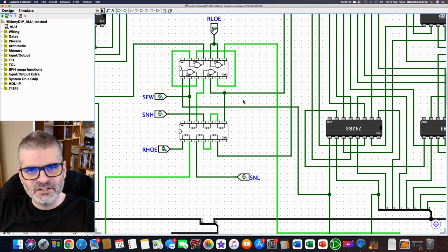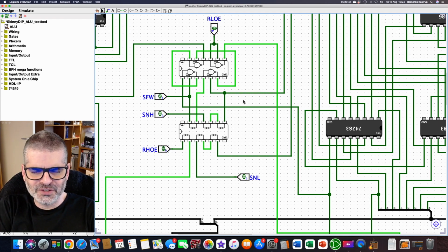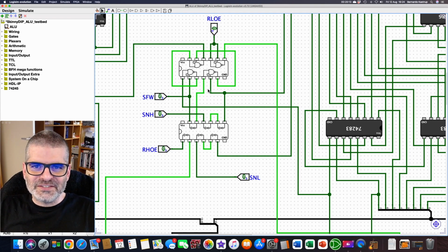If they hang the LEDs from 74 logic series, it's more than a current limiting resistor. You cannot use that pin as a logically valid signal elsewhere in the circuit either. But whatever he said or didn't say, the example I'm about to give you still holds. You can hang an LED from an output pin of a 74 logic chip, even without a resistor, and it will work for a while. Leave it on for several hours or a day, and you will see what will happen.